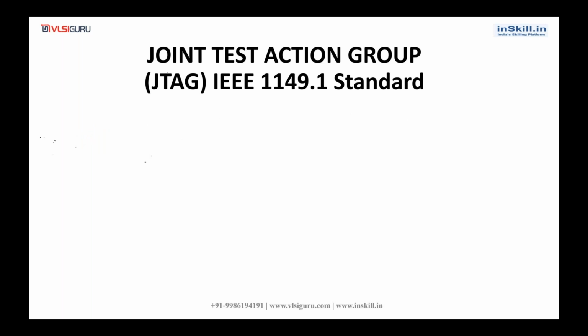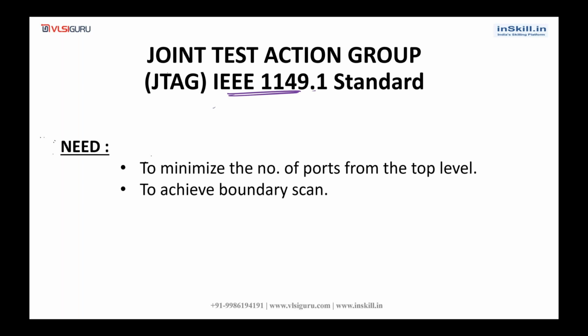And next is JTAG. JTAG is Joint Test Action Group. It's an IEEE 1149.1 standard. So why does the DFT team use JTAG? It is to minimize the number of ports from the top level and also to achieve boundary scan. That is why we make use of JTAG.